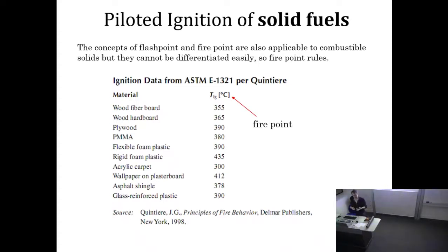You remember that it's a standard. You put the liquid into a cup. You heat up the cup very slowly, and you always pass by a pilot, and the liquid starts to pyrolyze or to evaporate, depending if it's pure or not pure organic. And then when it reaches a flammable layer at the location of the pilot, that ignites. And then you look at the dial, the temperature of the cup at that time, and you know that when the liquid is at that temperature, it can actually sustain above it a flammable mixture. And then you have the flash point.